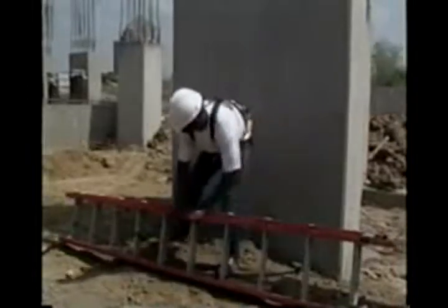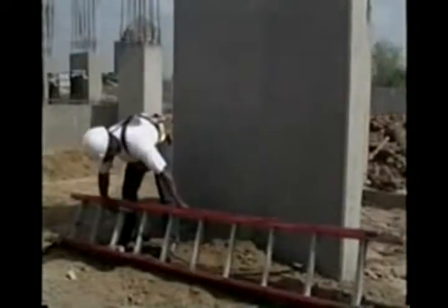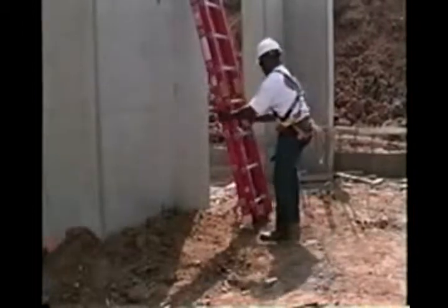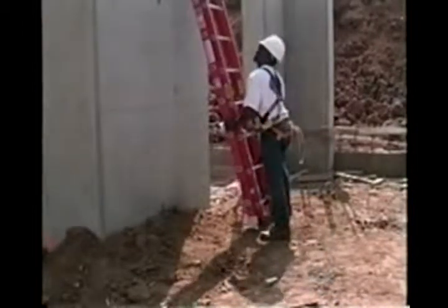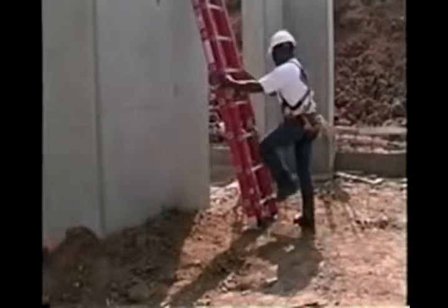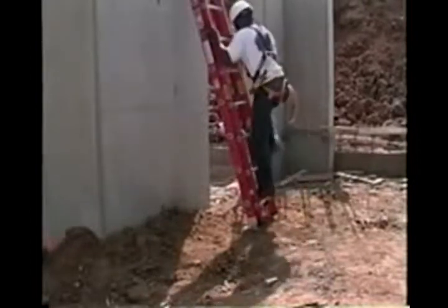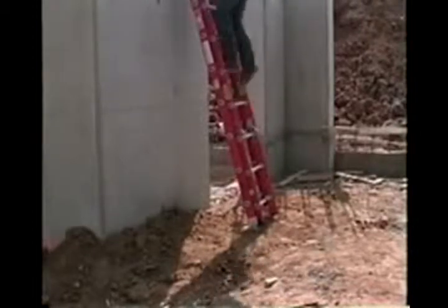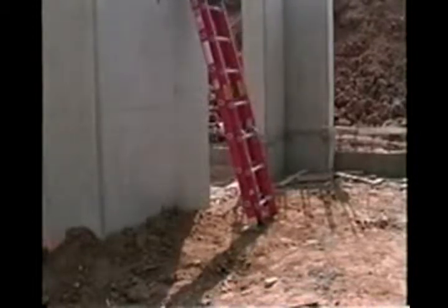Check the design strength of the ladder to be sure it will hold the amount of weight you'll be putting on it. To avoid having a straight ladder slip out from underneath you or from falling backwards, position the ladder so that the base of the ladder is at the most stable angle for climbing. The distance from the base to the wall should be about 1/4 the working length of the ladder.